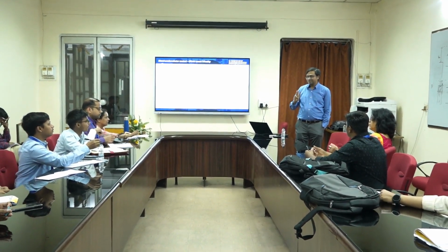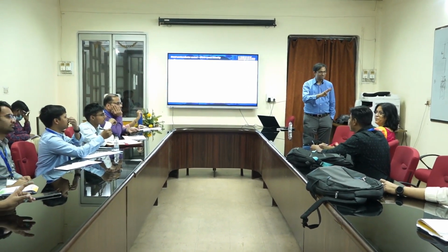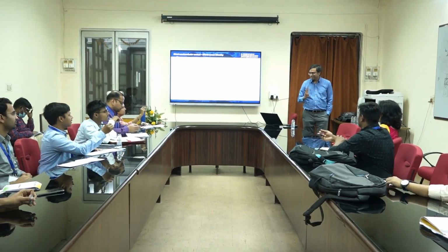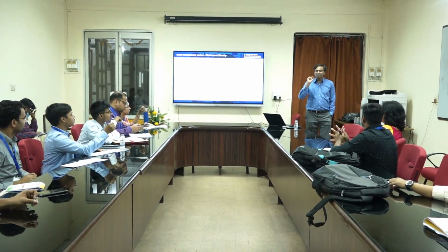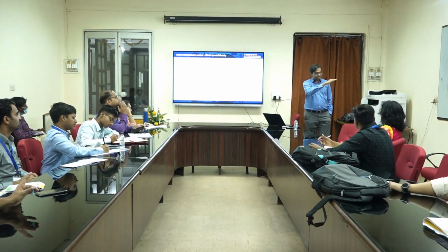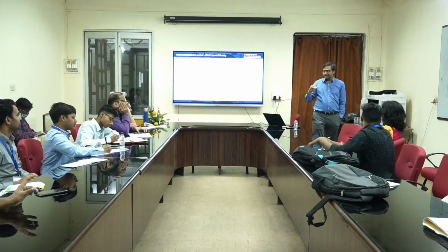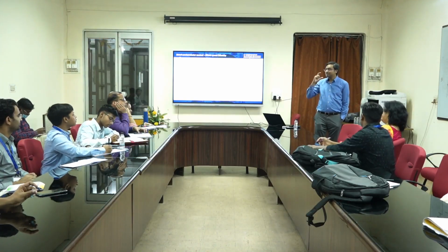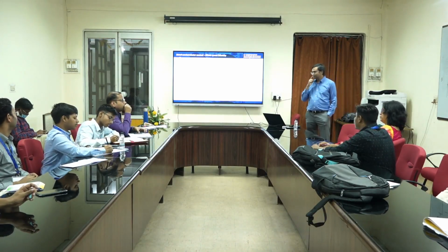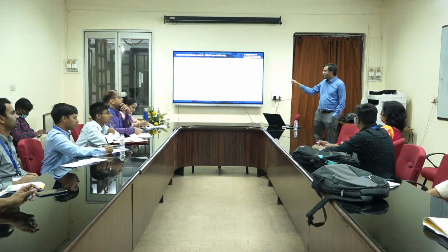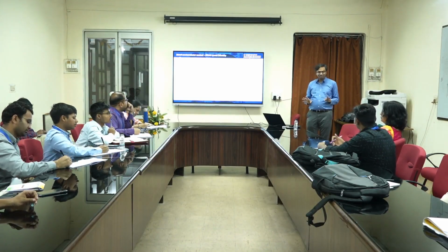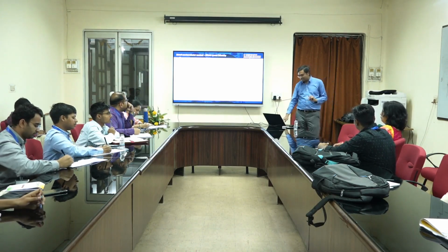And the third rule. Somebody else tell me the third rule. That is the most important rule. Okay, first two rules are easy rules. The relative position of the Fermi level, I mean the work function of the metal and the electron affinity, has to be the same with respect to the vacuum level. Chi, electron affinity. Good. Hopefully you remember these three rules. Then you will not struggle in drawing band diagrams ever.